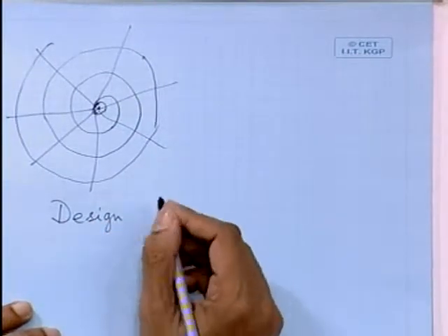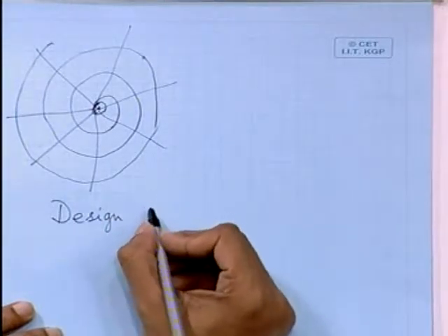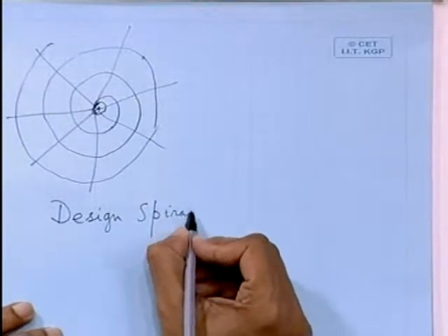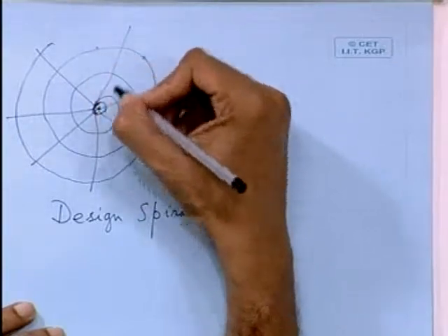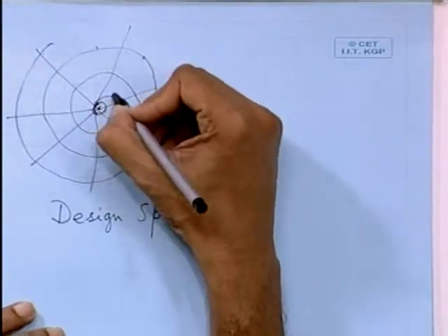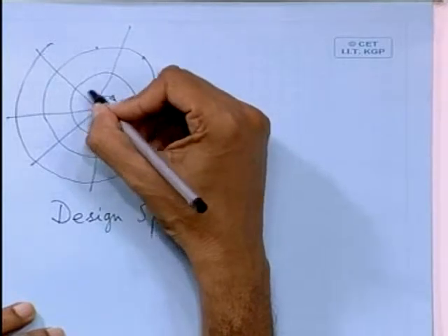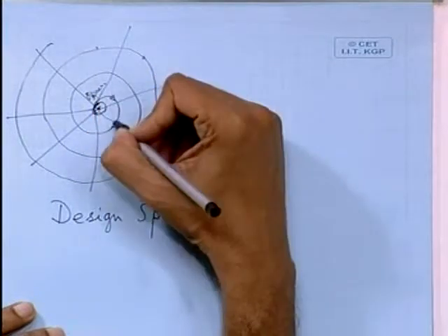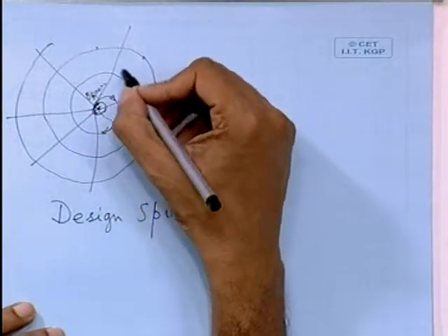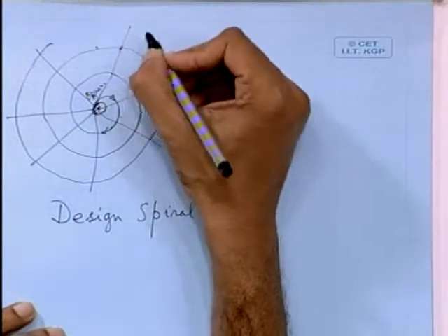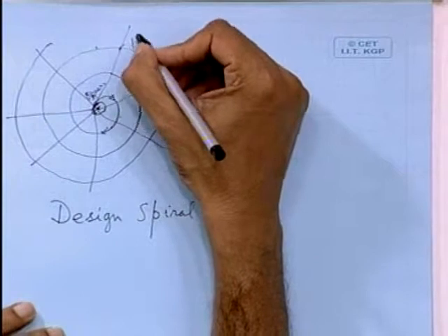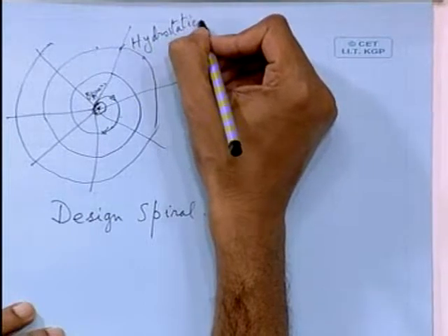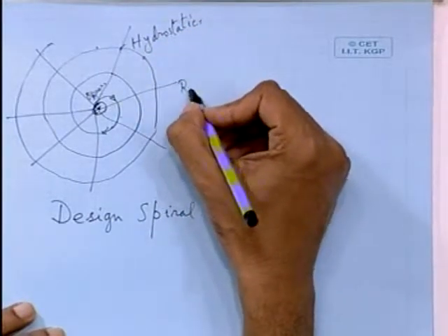Remember, at this stage, the preliminary design stage, the principal parameters have not yet been fixed. So here you start from the owner's specification, somewhere here, and you try to vary the parameters, and at the spokes, at this junction, you do certain calculations. The first calculation will be your hydrostatics, which of course another teacher will tell you. Next will be, say, resistance and propulsion.